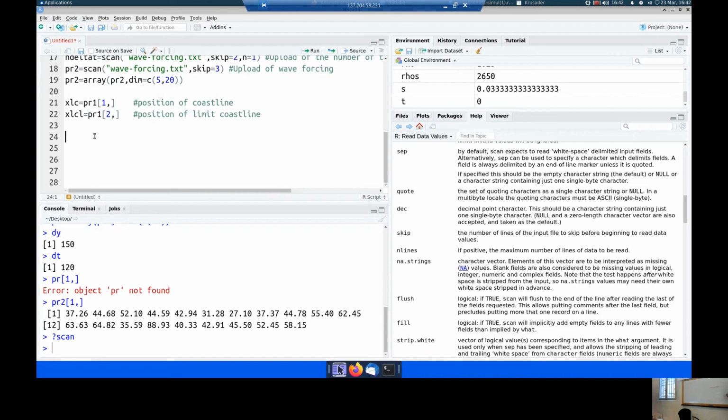And the same may happen with a groin. If you have a groin here, the effect is different. If you compute your sediment transport here, this constraint is not precisely the same because I'm not limiting the coastline. But what I say is that this QS here, if it is greater than 0, it's not transported here. So you put a limit 0 in that point.